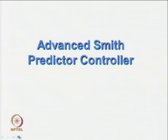We have got various types of processes, such as stable, unstable and integrating processes. Apart from these, we have also lag dominated and delay dominated processes. The Smith predictor controller is generally used for delay dominated processes, and we are going to discuss the conventional Smith predictor controller and some advanced Smith predictor controllers in this lecture.